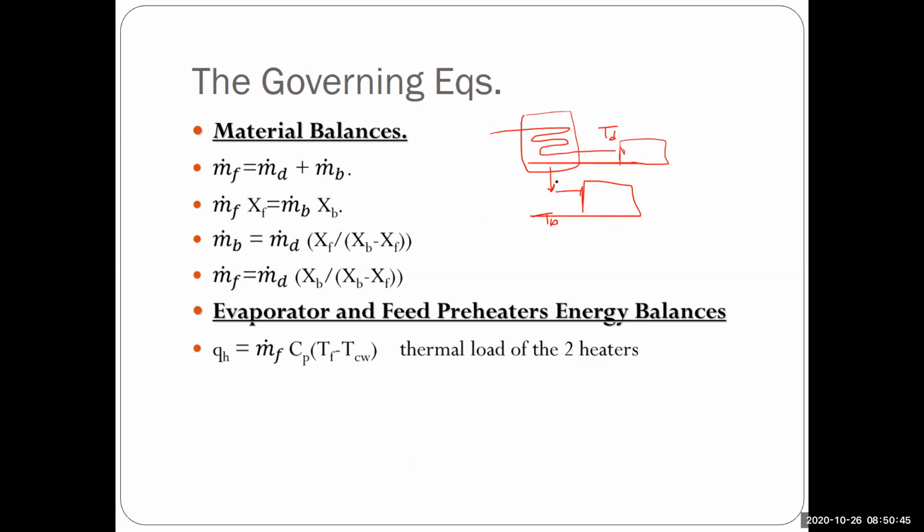Okay. So when it comes to the evaporator balance, the feed which is entering into the evaporator is going to be all of it heated to TB, then part of it will be evaporated and the rest will be rejected as brine. And the salinity balance, definitely the distillate here has a value of 0 salinity. This is the usual assumption for thermal distillation systems, and accordingly, m dot f xf, which is the salt balance, is m dot b xb.